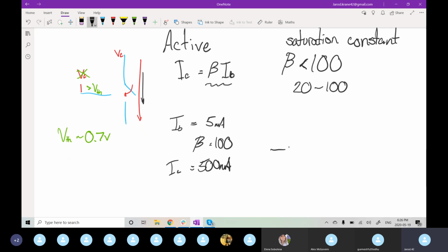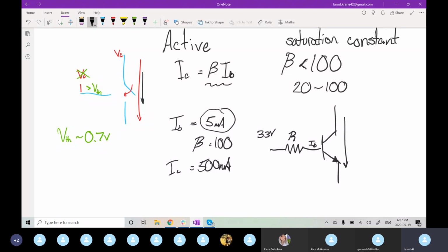And this is generally just done with a resistor on your pin. If you know you have a 3-volt signal, whatever resistance value you choose will give you your base current. So you're able to tweak your current to change your collector current that flows through.